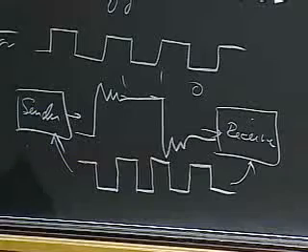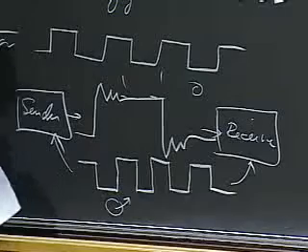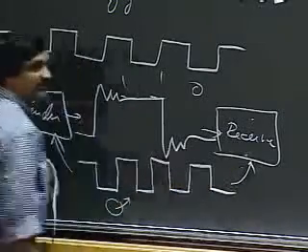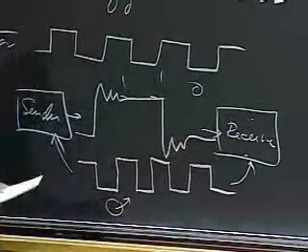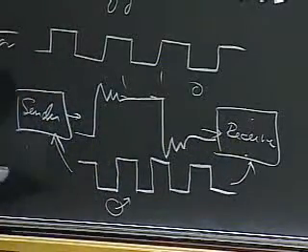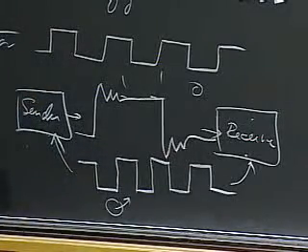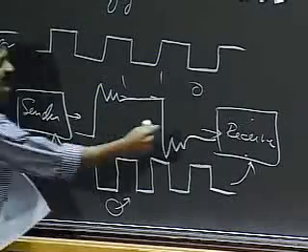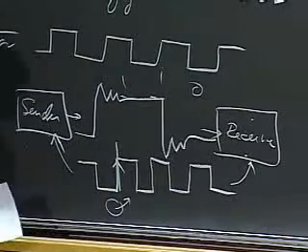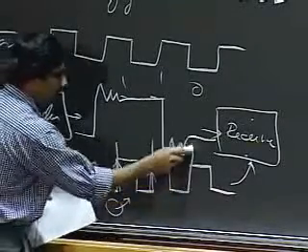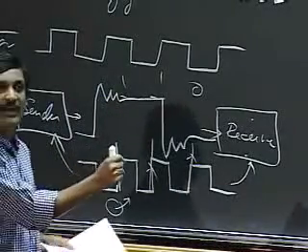A clock provides a notion of time to the circuit, and I have some kind of a clock signal generator, and I connect that to the sender and connect that to the receiver, and now both the receiver and the sender have a notion of time. And what I can do is I can tell my receiver, the sender and the receiver can have an agreement between them that says that look at the signal at your input on the rising edge of the clock.